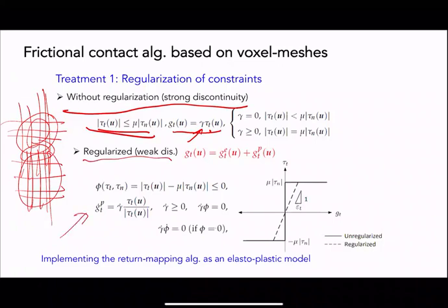We try to say that all the admissible tractions field in the tangential and normal directions are within the Mohr-Coulomb envelope. And we want to impose the classical positivity, but now apply it to the interface displacement field.